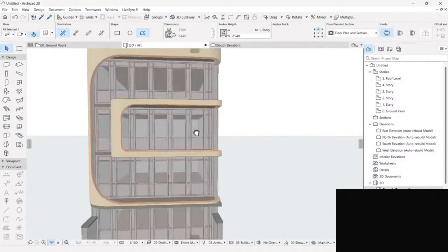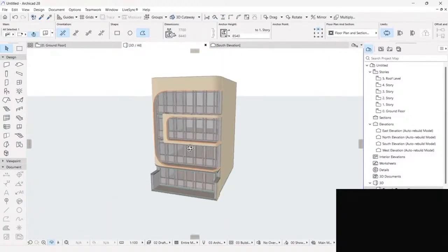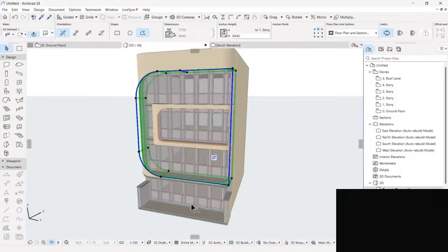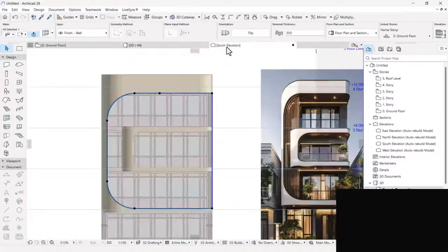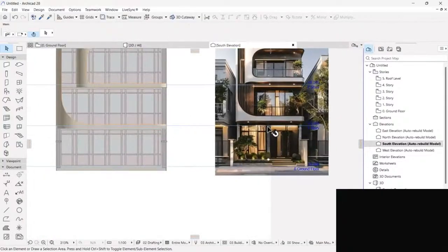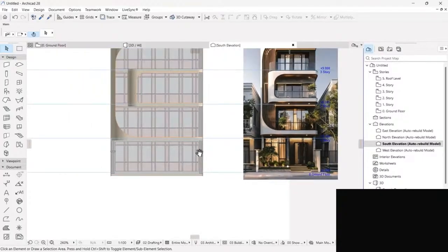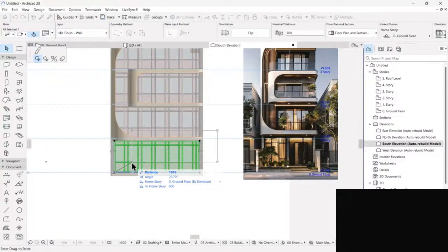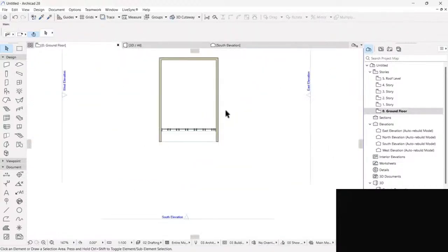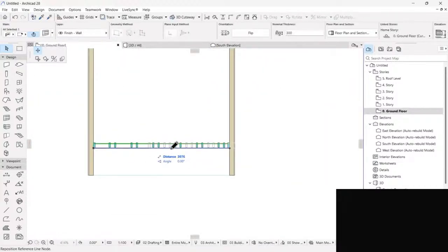Right, so we have now completed the features. We need to move on to the curtain wall styles. So from the ground one, if you look at the image, we had this cladding wall, and then we have the entrance door. Then the other side is going to be your normal glazing. So to replicate this, I'm going to go to the ground and stretch this to there.